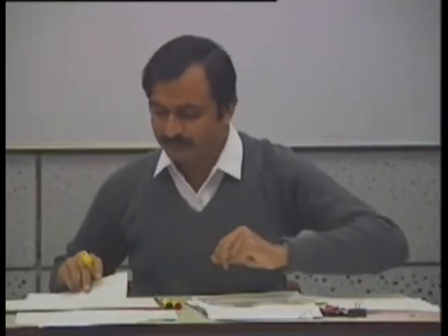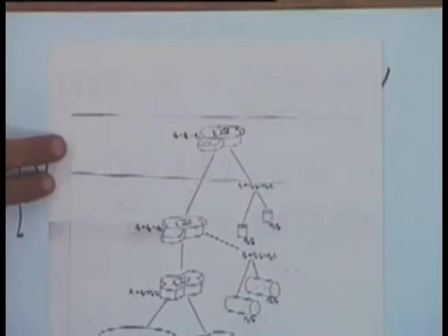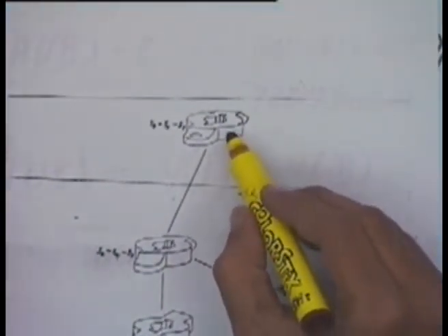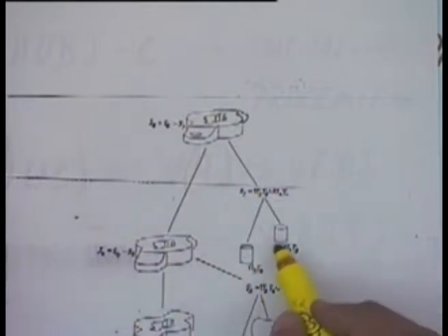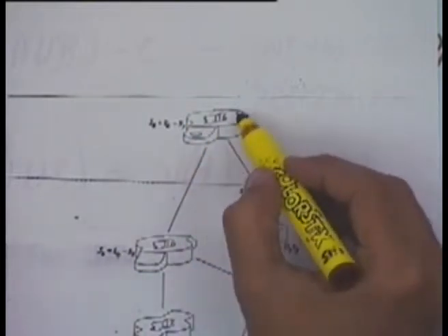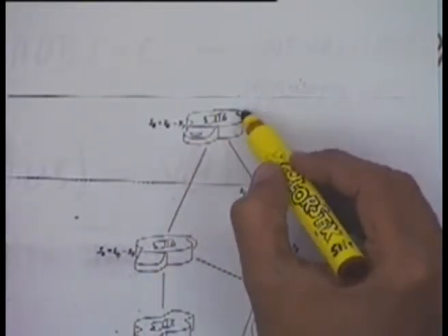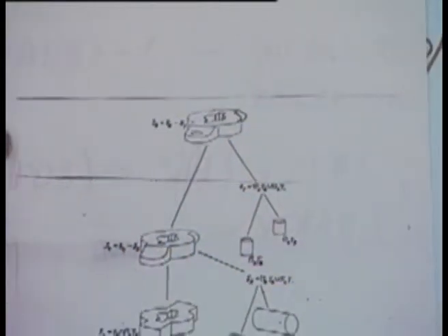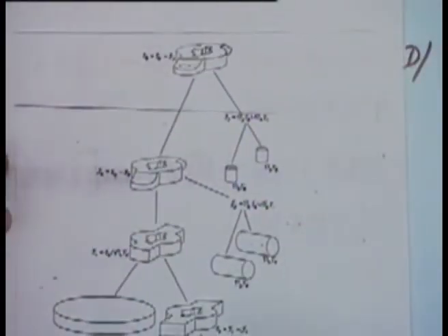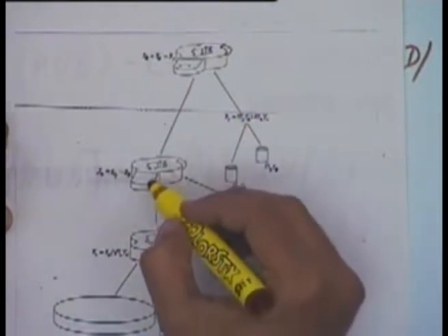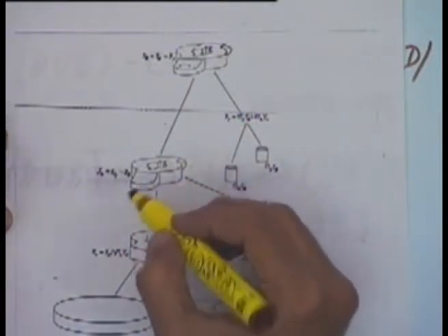Let's see one more example of how a solid can be constructed. If you have a solid like this, we can construct this solid by taking this solid and these two cylinders and carrying out the difference. I'll get these two holes, one hole here and one hole at the other side. This solid I can construct by taking this solid, and then these two cylinders, and again carrying out the difference to get these two curves.